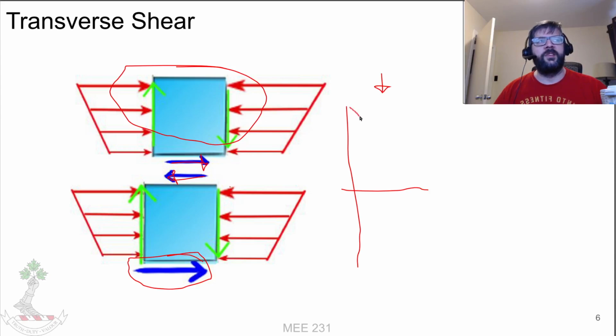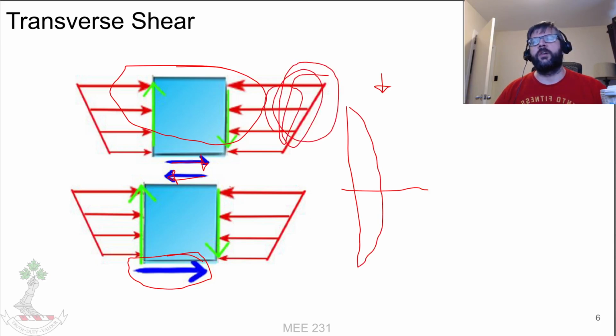It increases, and the rate of change is directly proportional to the stress caused by the moment there. So essentially, the rate drops until it hits 0 at the neutral axis, and then it continues to drop, just becomes negative, which means that the shear stress drops down to 0 at the other end.